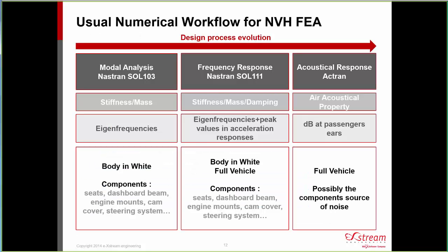So today, this is a basic drawing of the usual numerical workflow which is followed for NVH FEA. Here it's a case where the user is using Nastran, of course. Nastran is well known for its capability for NVH analysis. Whether we talk about doing analysis at the body in white level or on components, it always starts with Nastran SOL 103, modal analysis. We always need to evaluate the modal basis of the parts or the vehicle.